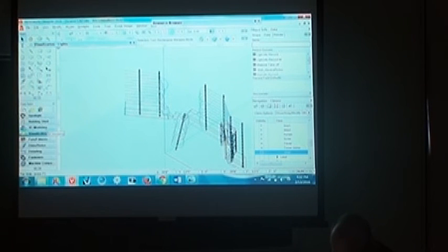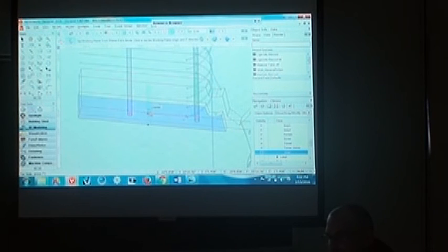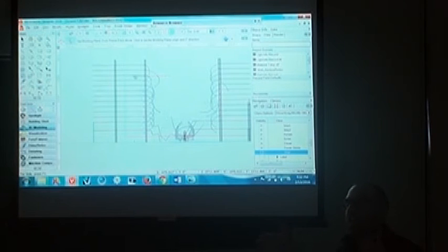One way I can do that is to, again, go back to my custom working plane. And I'm going to select by a face. I'm going to choose the face of that section of the wall because that's what I want to look straight at, right? And I'm going to say, look at the working plane. And now I'm looking dead on that section of the fence, right?